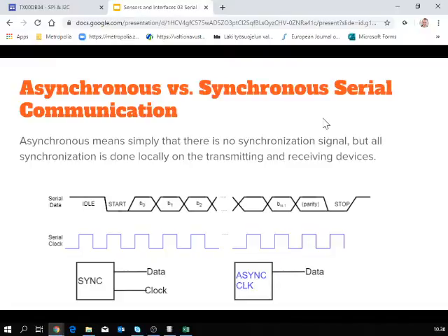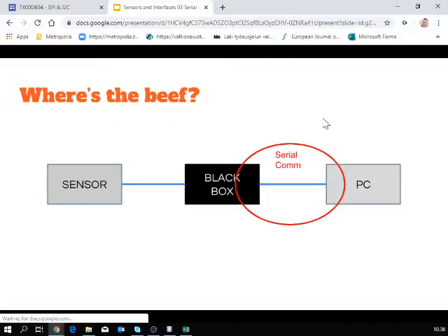That's the usual way of transmitting. Basically, the start bit edge tells when the local synchronization should start, and then there's also the stop bit just to have a gap between these consecutive transfers. But this is at a general level.